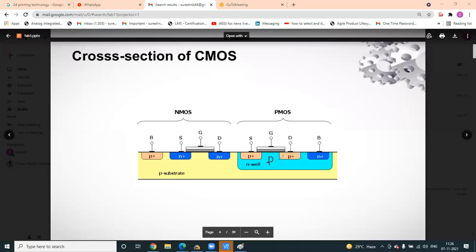So this is your PMOS. You need to connect the body. How is it connected? Here it is called the N tap. This is your NMOS. To connect that body, you need a P tap. Don't get confused; some people ask whether for NMOS you place an N tap or a P tap. Is this clear, or does anybody have a doubt? Somebody asked why you cannot connect the body directly to metal. This is a metal. How can you connect a metal to a semiconductor? The doping percentage should be high. You cannot directly connect a conductor to a P substrate, because the P substrate is lightly doped.